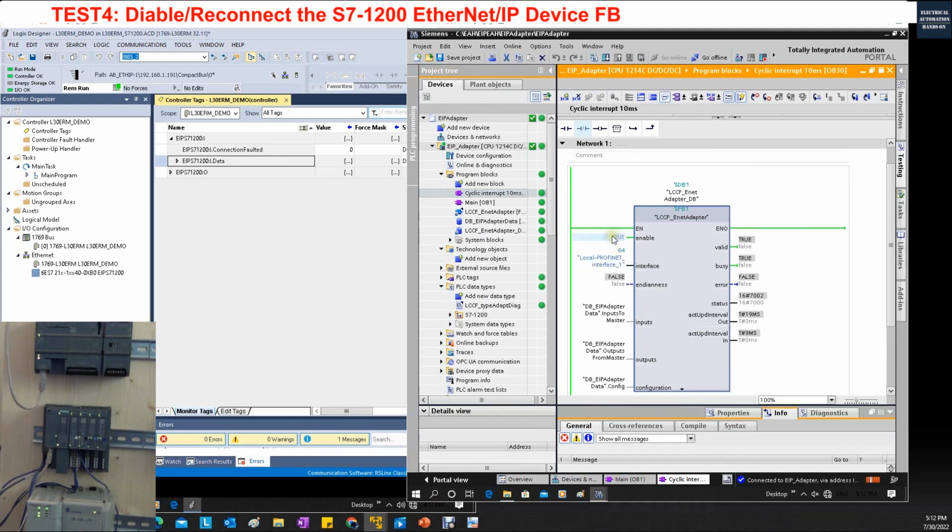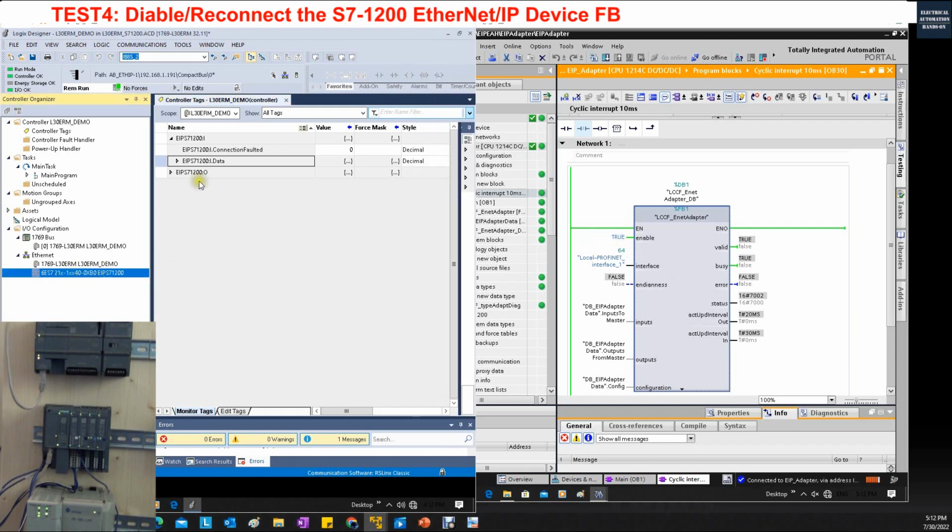So maybe setting true would be a good idea, or you can give a command, and after the Siemens controller powers up and starts up, you can enable. But once you enable, do not disable it after the communication is set up. Okay, give always true. We'll see this communication is now on.